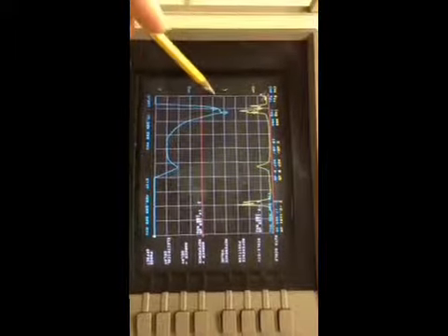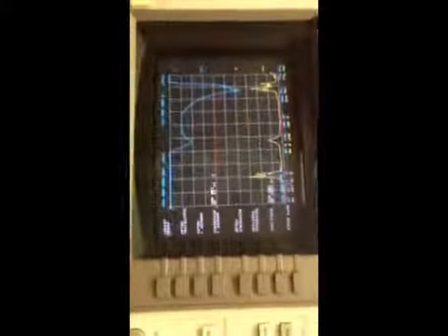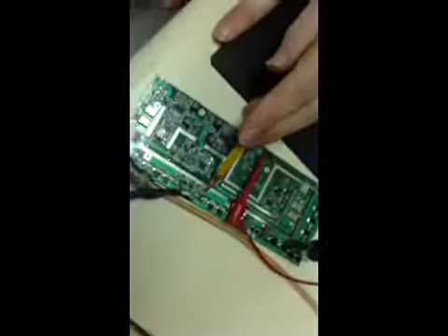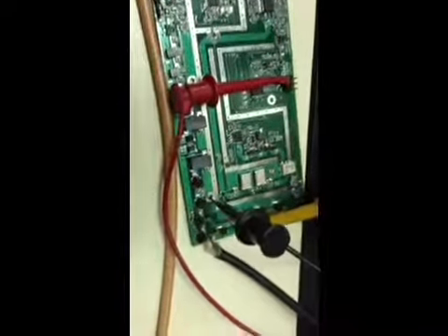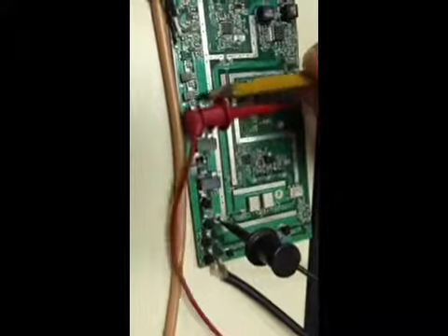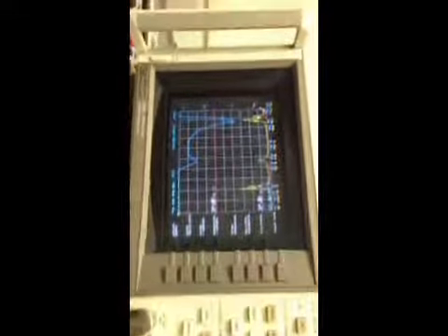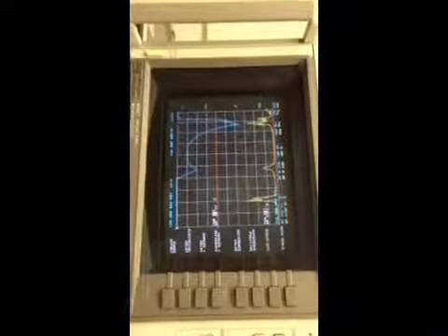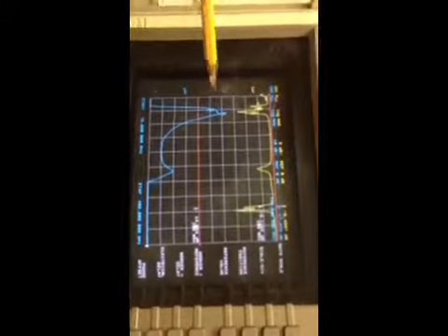At point 1, we're seeing 14 dB of gain. The reason we're seeing gain here is that on the board we have a 20 dB low noise amplifier where we're pulling off the signal. So we're seeing the notch filter and frequency split, as well as the first stage of the VOR filter and the first gain stage. The fact that with a 20 dB amplifier we're only seeing 6 dB of loss is well within our requested spec for 108 megahertz, which is significantly better than our simulation.